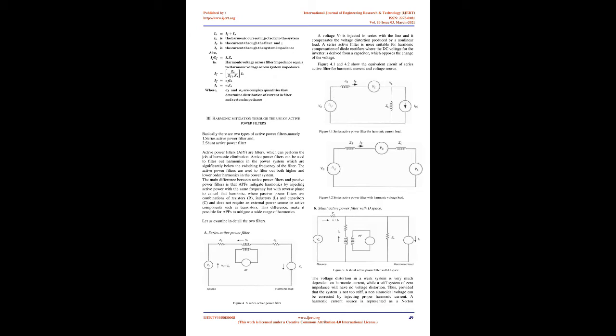Single-tuned filter. The single-tuned, ST, filters are efficient filters and will bypass a certain harmonic to which these are tuned. These are the most widely used filters in all applications of harmonic mitigation. However, care is required in their design, so that the components are not overloaded, and overvoltages due to their applications are controlled. Many times a group of ST filters are applied, each tuned to a specific frequency. The operation of an ST shunt filter is explained with reference to Figure 3.